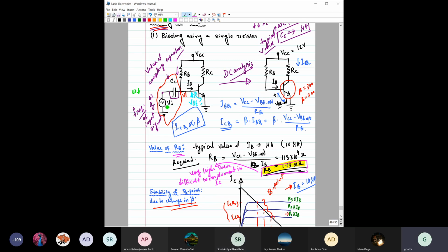Then what would be this voltage? If you apply one small KVL here, then the voltage at this node would be equal to this AC voltage minus the drop across the capacitor. Do you agree? Yes, sir. Now, if the voltage drop across this capacitor is more, then more part of VI will be dropped across this capacitor and less part will be coming across at this node.